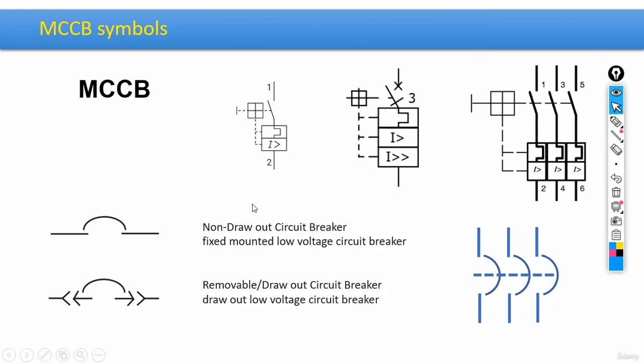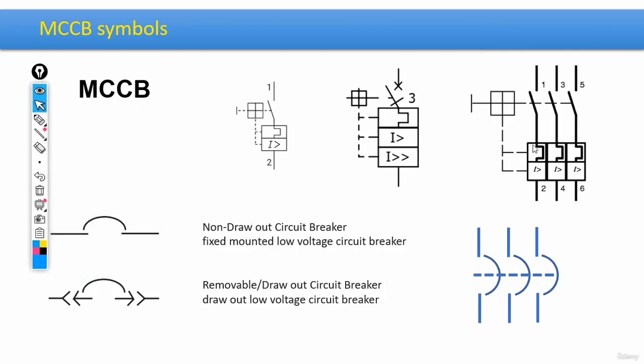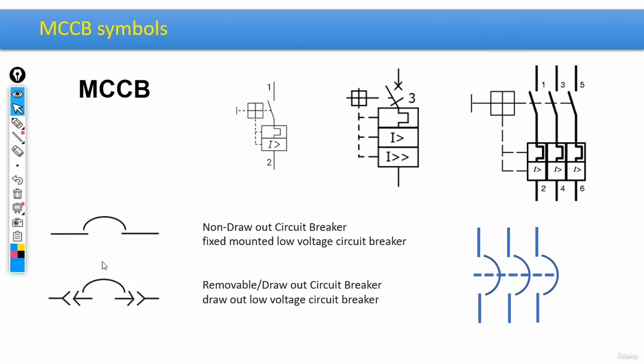For example, we got an MCCB breaker symbol, single line. Okay, this one is also a single line MCCB breaker symbol. This one is used for circuits with high electrical current. Then here we got a multi-line MCCB symbol containing symbols for both overload and short circuits, okay? And by the way, the symbol that you can see here would be the American version, based on the NEMA standards.